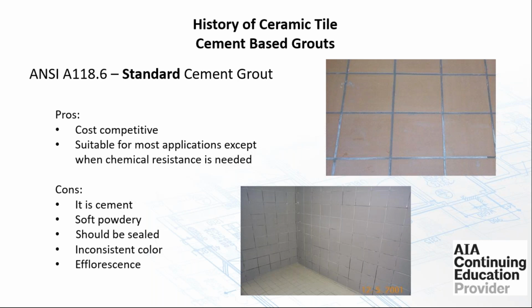As an example, if 2 or 3 of us are doing a floor and I start in the back corner of the room, and you're near a window where the sun is beating in, and somebody else is by an open door, I can almost guarantee you that the shading of this grout will not be the same going across this floor because of the various things affecting the drying time of this grout. So you can end up with inconsistent color.